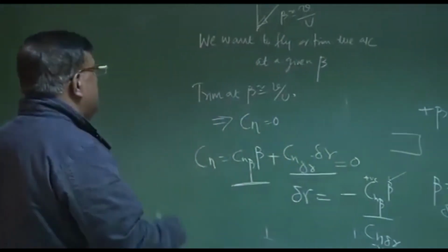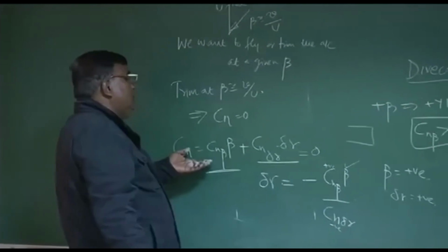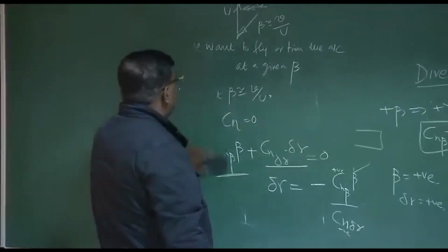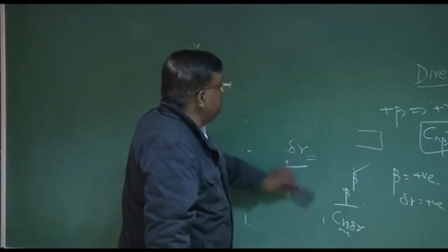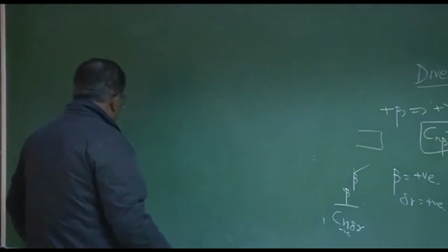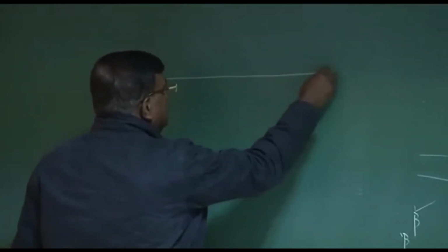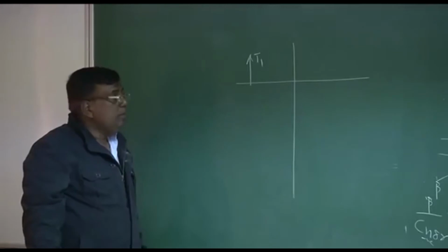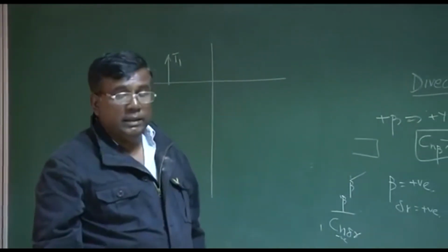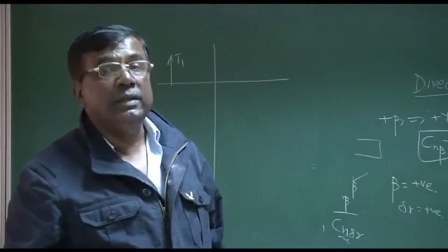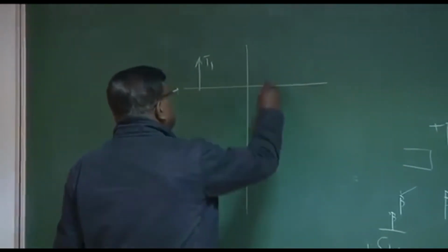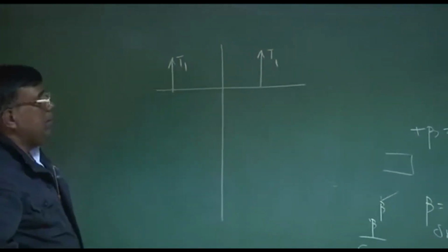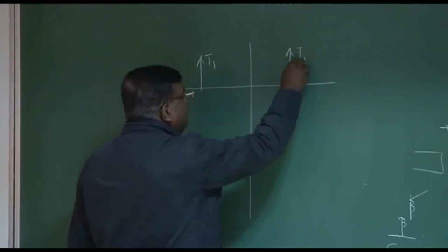Now, this was simply me talking about your rudder control, and rudder, if you remember, one of the important things which rudder should do is the engine failure case. Okay, let's also revisit that. It's very important. This is the wing, and let's say this is the fuselage and all. Now the important aspect in the directional case is basically for a twin engine airplane. Right? You know, in a twin engine airplane, there are two engines. Let's say both are having the same thrust, but there is a possibility that one of the engines can fail.